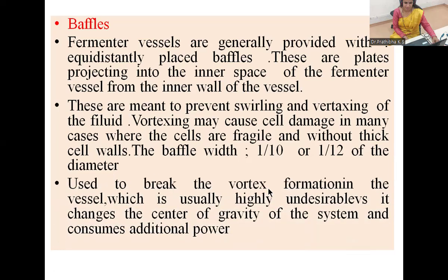And these are used to break the vortex formation in the vessel, which is usually highly undesirable. It changes the center of gravity of the system and consumes additional power. I hope you're able to write about the baffles for 2 marks. I hope you understood the purpose of fitting these baffles inside